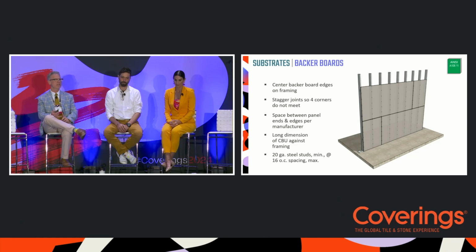So let's look at cement board, or just more generally a backer board. Okay, a few things we need to have are backer board on framing, whether it's steel stud or wood stud framing. It has to be stiff, right? This backing has to be stiff enough so that the finished tile installation does not deflect, and the grout joints don't crack when somebody slams a door or when somebody bumps the wall or leans up against the wall.